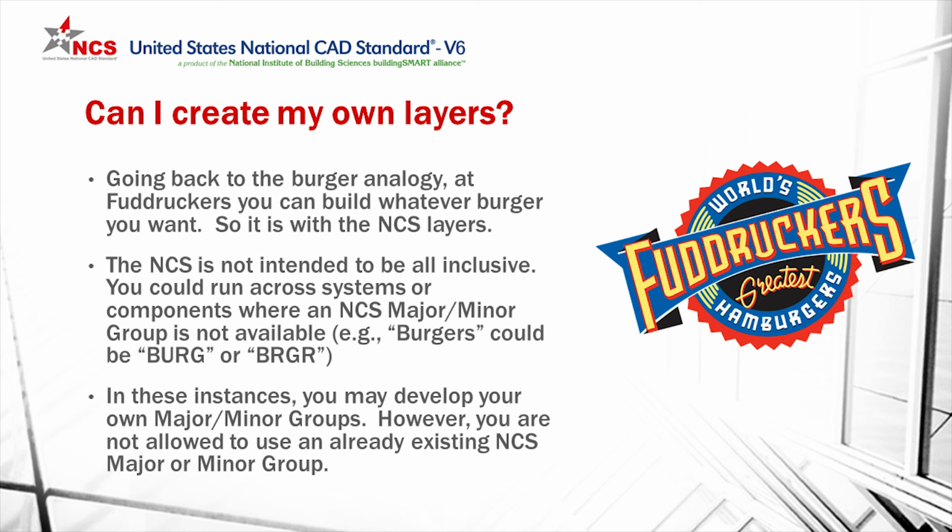The same thing goes with the National CAD Standard. You can build whatever layer list you want, and if they don't cover something in the National CAD Standard, you can build your own layers. This is silly, but let's say I needed a layer to cover burgers. Obviously, there isn't going to be a layer for that in the National CAD Standard. So what I could do is create a major group called BURG or BRGR, and that could cover burgers.